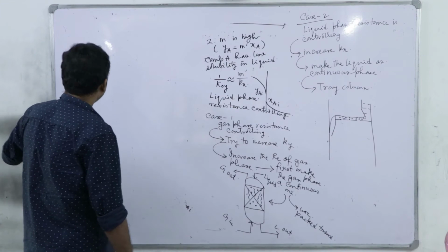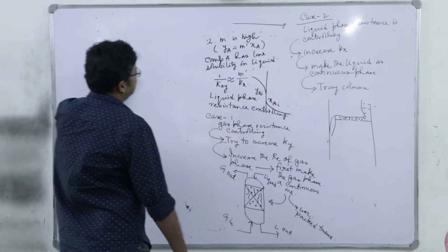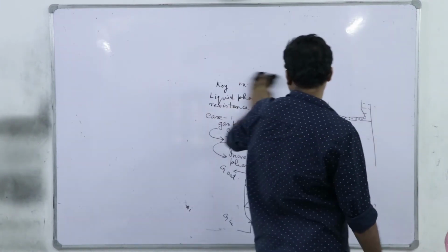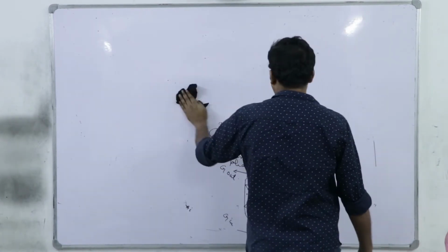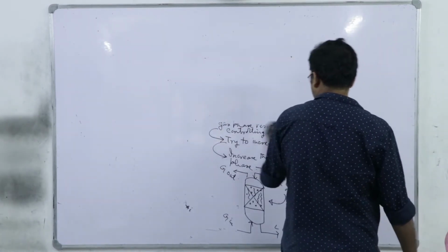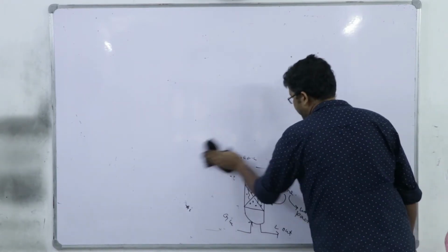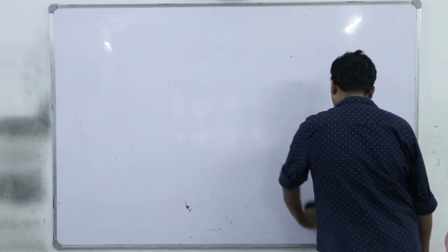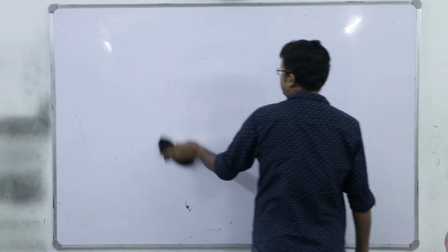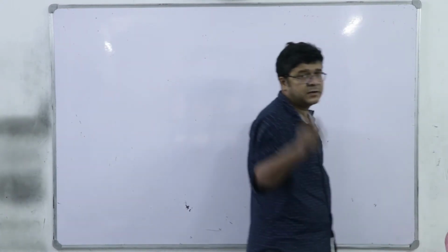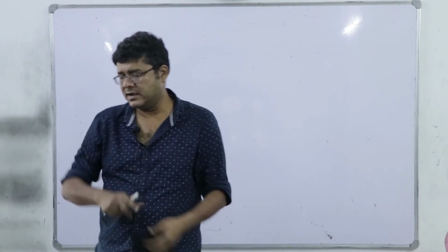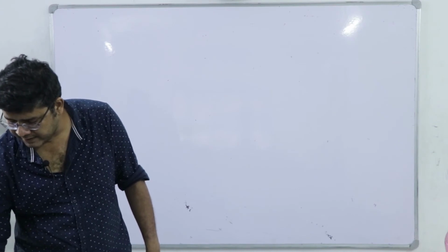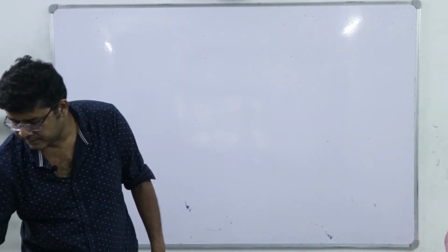Okay? So with that idea of interfacial mass transfer, or these interfacial separation techniques, let's now go for understanding the mass balance over a typical exchanger without specifying its internals, like whether it is a packed tower or a tray tower. Without specifying the internals, let's write the material balance over a mass exchanger, considering this entire thing as an envelope, right? And from there we will try to understand the idea of operating line.